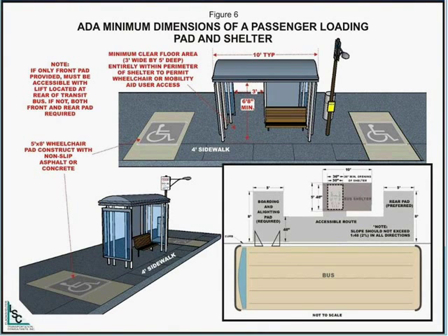There are many criteria that have been set up by the Americans with Disabilities Act in the designing of a bus stop, and this tries to articulate the various considerations, considering the curb cuts and the slopes and the size of the various facilities, so that a person with a wheelchair can maneuver around the various appurtenances that may be located at the passenger loading and the shelter area.